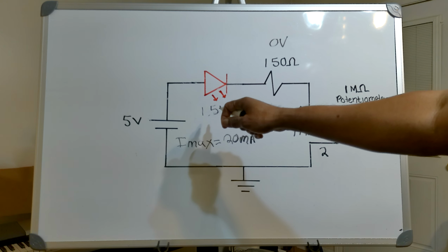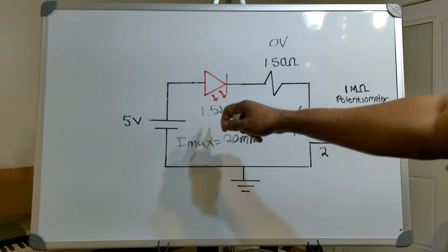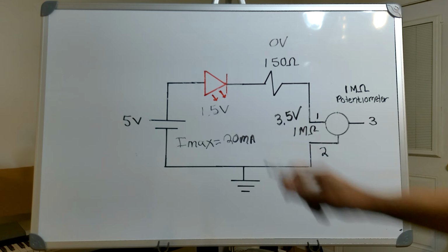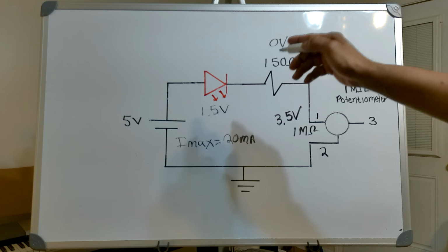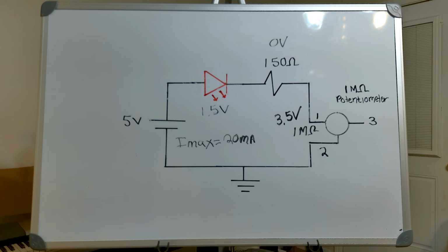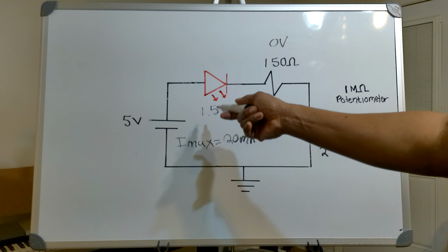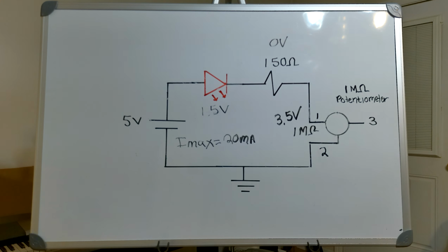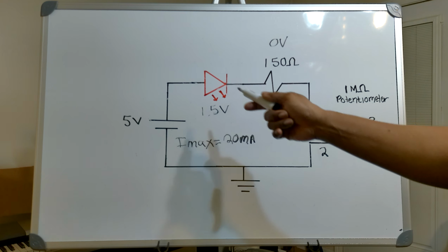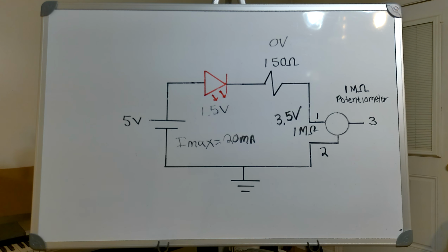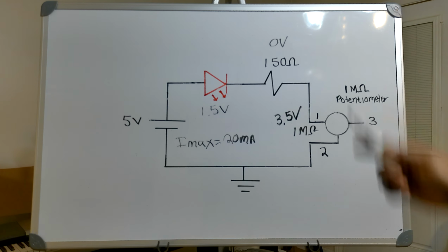What you've got here on the LED is what's called a threshold voltage. And for the red 2-volt LED, the threshold voltage, I believe, is somewhere between 1.3 and 1.5. Some of them are about 1.4. But for all intents and purposes,